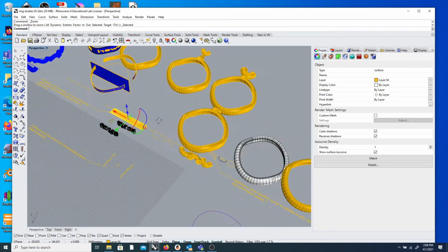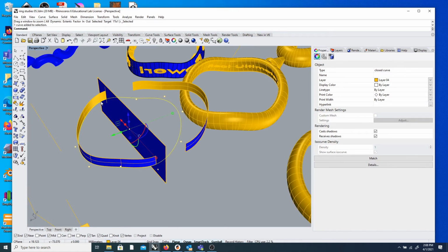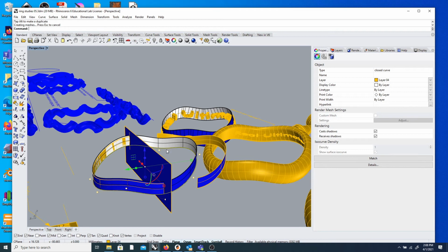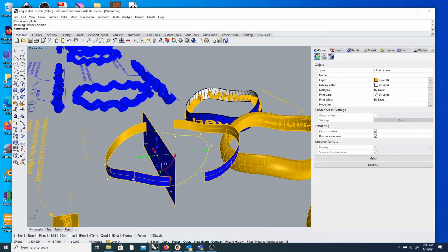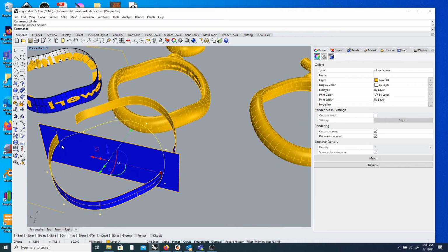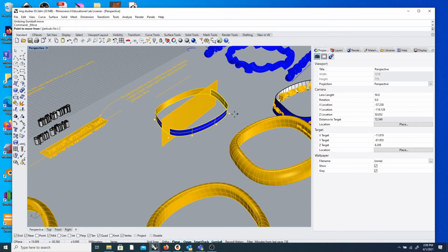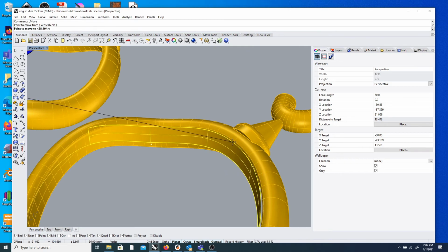Okay. And we have taken the ring band curve that we had before. It doesn't matter if it's just a circle or a manipulated circle like I have. And then I've swept a line around it. Or you could probably even extend your curve out like that if you wanted to, like with the gumball. I think that may have been what I did for this bit, but you can sweep it as well. And then you divide that into a section that you want your text to be on, okay? And I think the whole time I was doing this, I had moved this into the space.